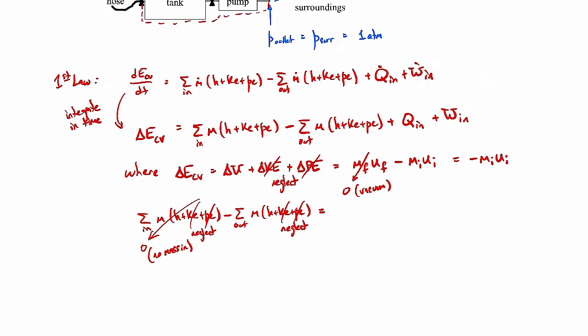When you're dealing with air, the potential energy of the air is typically very small because the density of air is very small. The kinetic energy at the outlet could be significant depending on how small the pipe is and how fast the air leaving that pipe is going. We're not told any information about that, so we're just going to go ahead and neglect it, assume it's small, because we weren't really given any information. If the pipe has any kind of a large diameter, those velocities are probably pretty small anyway compared to the specific enthalpy, so it's pretty reasonable to neglect it.